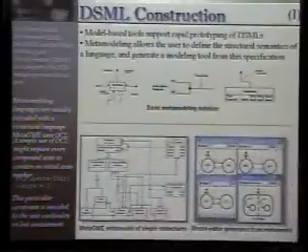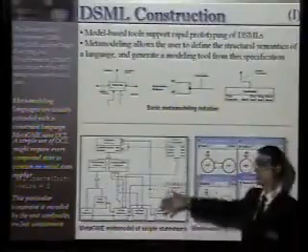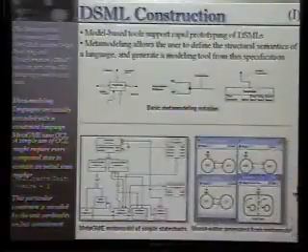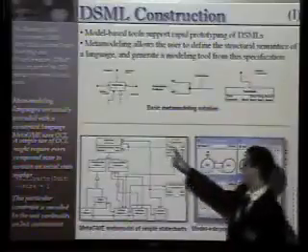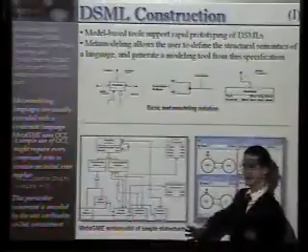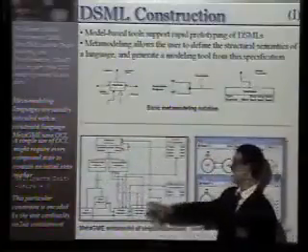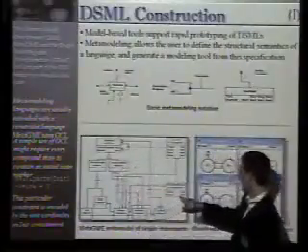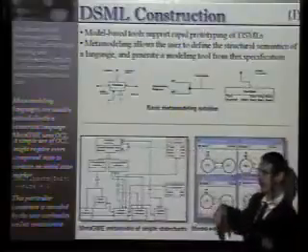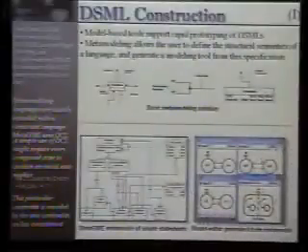This meta-model describes sort of an automata-based language. You construct this meta-model in GME. GME interprets this meta-model and then generates for you a modeling environment that lets you construct domain models. So for example, this one describes, I'm not sure how easy you can see from back there, a hierarchical finite state machine. So you have things like compound state and primitive state. These inherit from some state base. States can be connected by transitions. Here, transitions have triggers, guards, actions. So you specify all this information, you just give it to the tool, and then out pops a modeling environment that lets you build hierarchical finite state machines. So it gives an interpretation to this picture, and then you can construct your models.